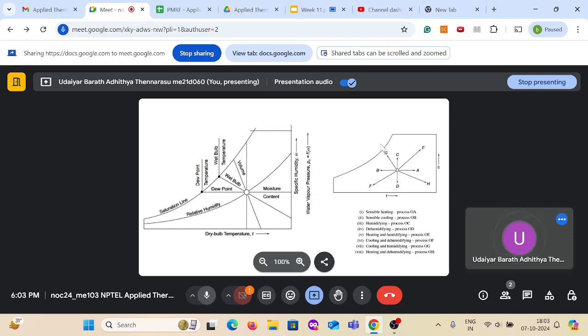This is again because of the frequent opening and closing of the door, the air is entering there and is getting condensed and frozen on this freezer compartment. So the air is not just air, but you have your dry air and some amount of moisture present in the air. So that too needs to be studied. So that's why the psychrometric.